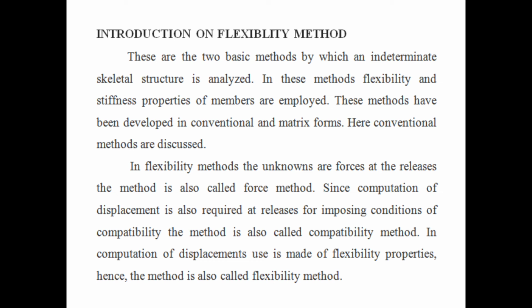In flexibility methods, the unknowns are forces at the releases. The method is also called the force method. Since displacement is also required at releases for imposing conditions for compatibility, the method is also called the compatibility method. In the computation of displacement, use is made of flexibility properties. Hence the method is also called the flexibility method.